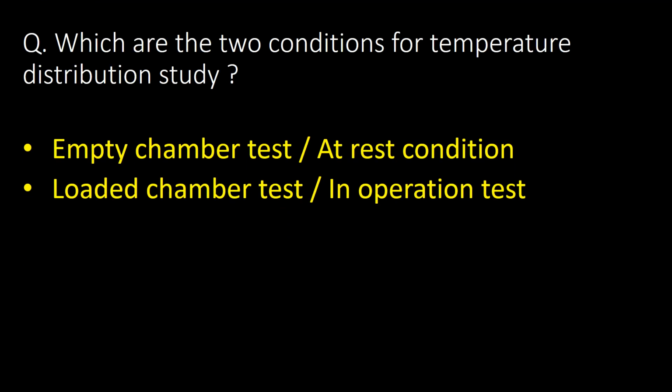Next question, which are the two conditions normally considered during temperature distribution study? In case of chamber temperature distribution study, we consider two cases: empty chamber test and loaded chamber test. Whereas in case of processing areas, we consider two conditions: at rest condition and in operation condition.